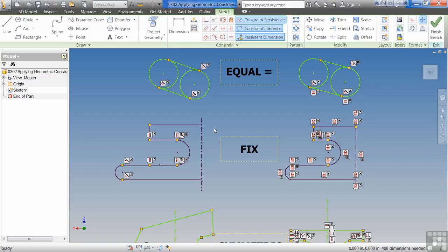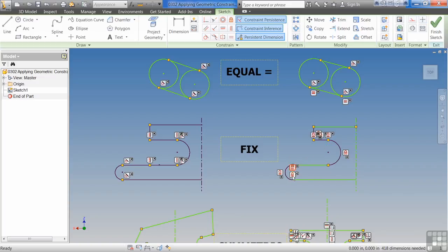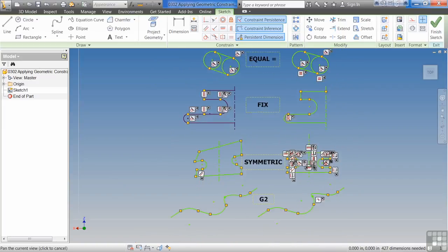It could get very frustrating if you came into a very complex sketch and a part of it was locked and you couldn't figure out what it was to be able to adjust it. I always tell people if they use the fixed constraint, use it sparingly and then turn it off when you're done. Easiest way to turn it off is just select it and hit delete on your keyboard. Ideally, you wouldn't be doing this many points whenever you're doing a locked or fixed constraint. But try not to leave it locked, because it could come back and bite you later on.